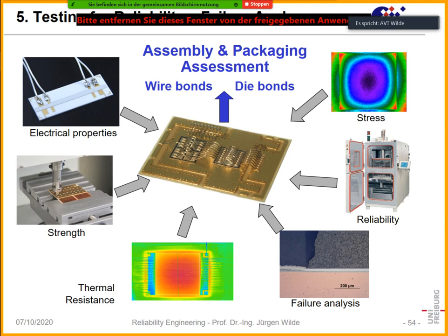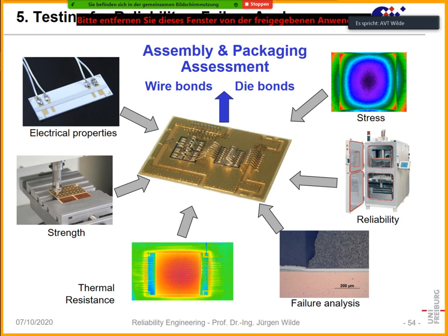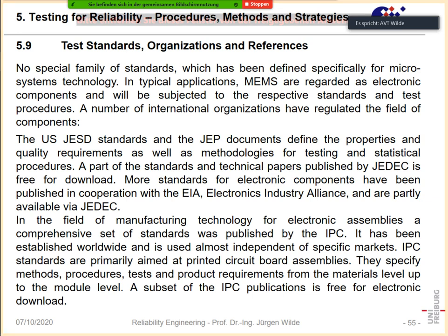One of my PhD students has developed test equipment to measure the thermal resistance. So if in the testing suddenly the thermal resistance goes up, temperature will go up, and that is a good hint to show us there are cracks developing inside here. Of course, post-mortem, I have shown you all of the failure analysis, and what is also always necessary is to have several different tests of reliability, because only after these you can do the failure analysis.